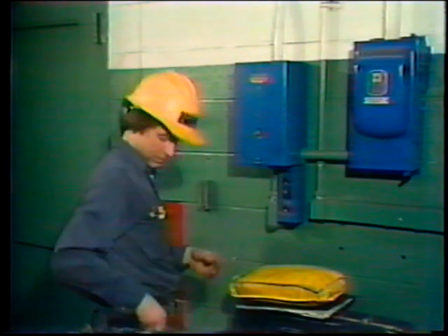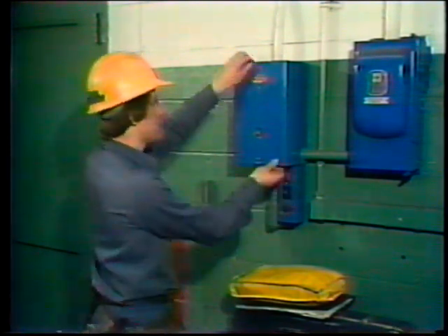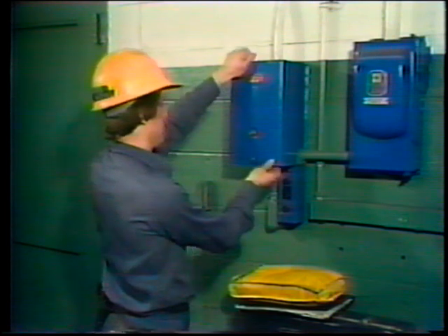Now he needs to locate that area and its components in the actual controller to inspect them, to try to determine if the maintaining contact or the wiring leading to the maintaining contact is causing the malfunction. The electrician turns a screw to loosen the cover to the controller cabinet. Then he removes the cover.